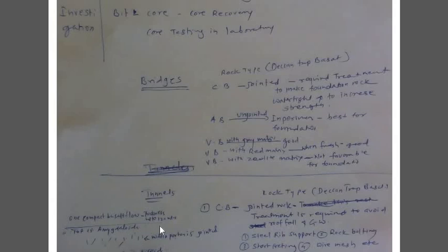So you can excavate a tunnel through this amygdaloidal basalt without any problem. But if you excavate a tunnel through the middle portion, the tunneling will be problematic, meaning you have to face problems. The best example of tunneling in compact basalt and amygdaloidal basalt is tunnel number 26. The diagram is given here.